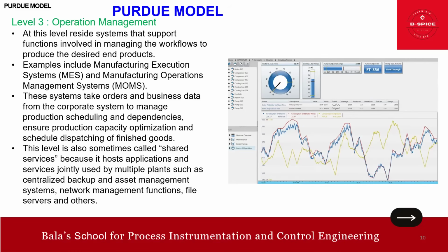Basically what the PIMS does here, it collects and integrates the information about production process infrastructures from a multitude of different sources, including the local historian from level 2. The historians use specialized algorithms for lossy and lossless data compression to reduce the storage footprint, as well as specialized software to enrich the data with context and visualize statistical trends, something like this. Right, friends? So that's about level 3.